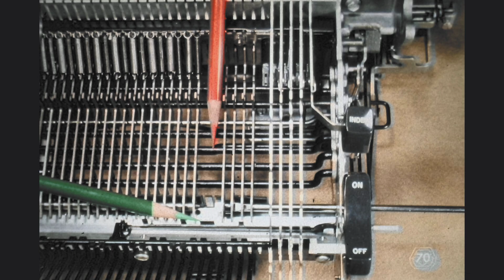We conclude, therefore, that even if there aren't any lugs under the underscore interposer to filter out selector latches having to do with tilt and rotate, there is one latch which will be selected, namely the low-velocity selector latch. By using low velocity to print underscores, the machine prevents the cutting of the paper.